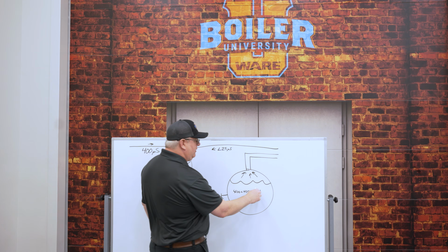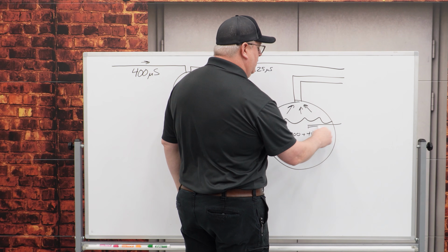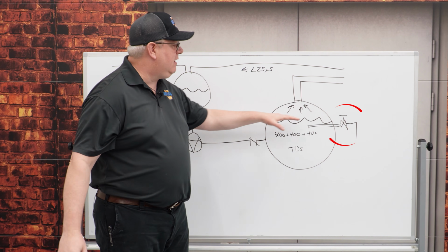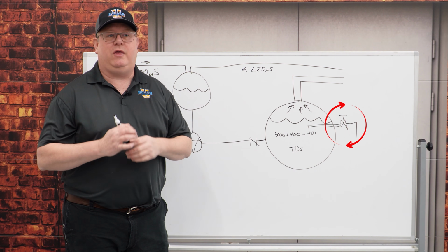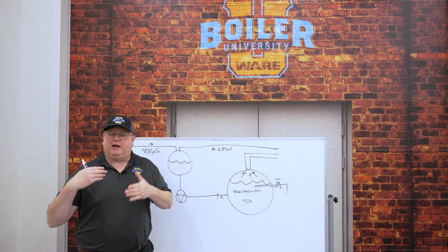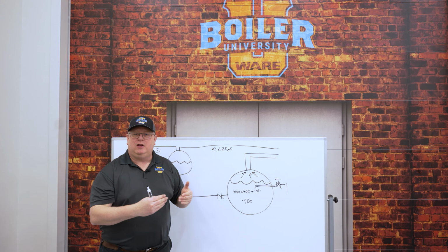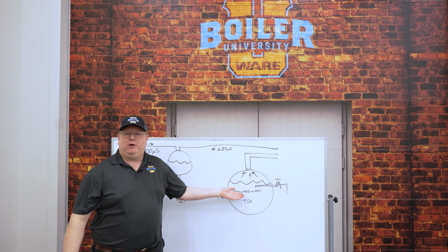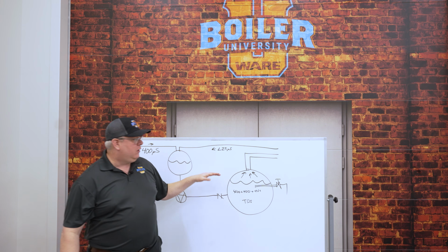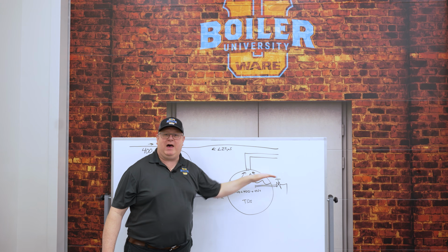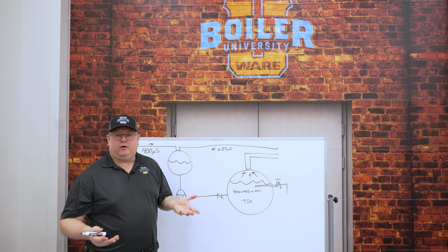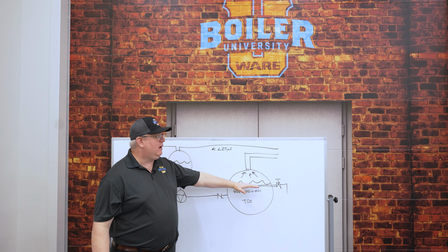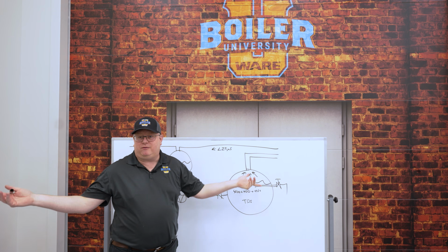So in a simple system, we would have a skimmer tube with a valve, and we would throttle that. And what that skimmer is going to do is basically throw away some of that water, because it's like gravy getting thicker on the stove. The only way to make that gravy thinner is to add more milk to it, but we don't want to overfill the boiler, so we have to skim some of that water so that the conductivity will come down over time. If the conductivity never comes up, that valve may be left wide open.